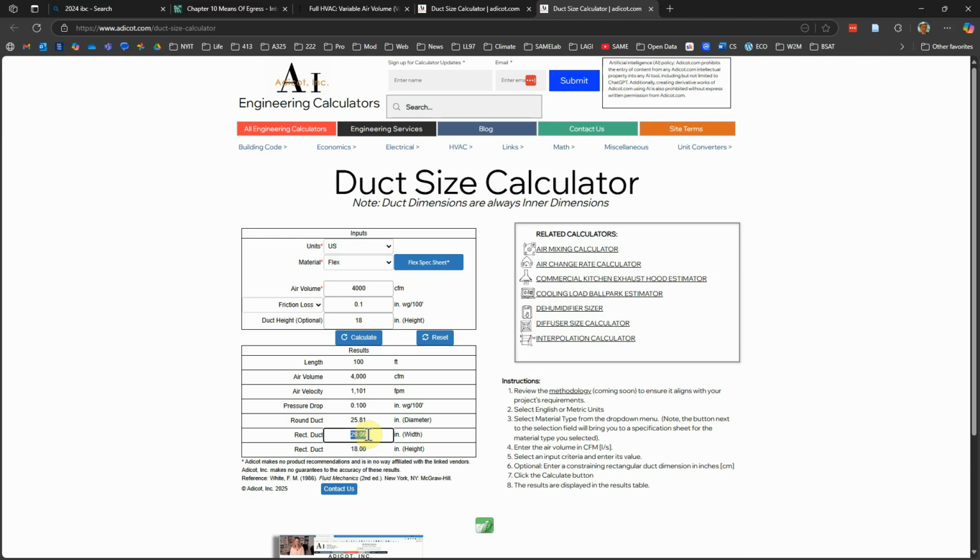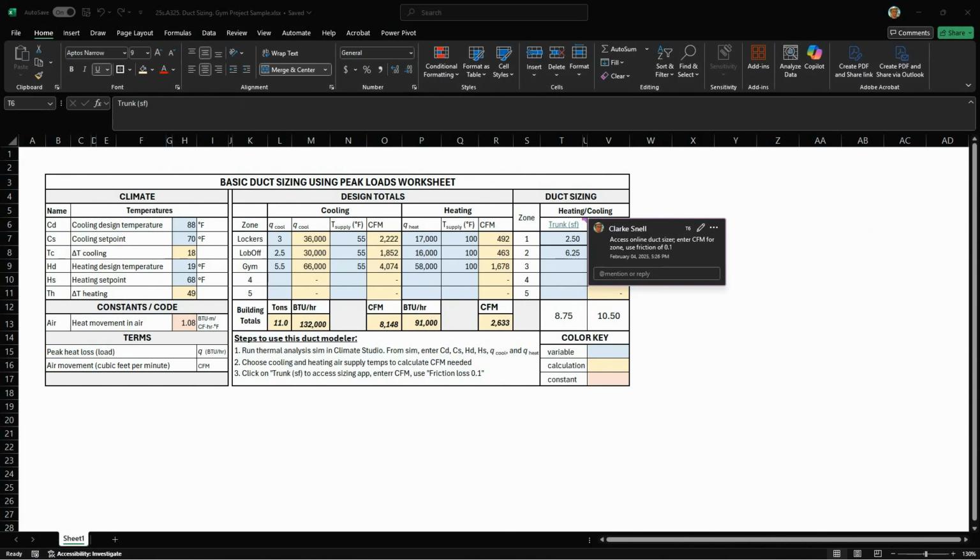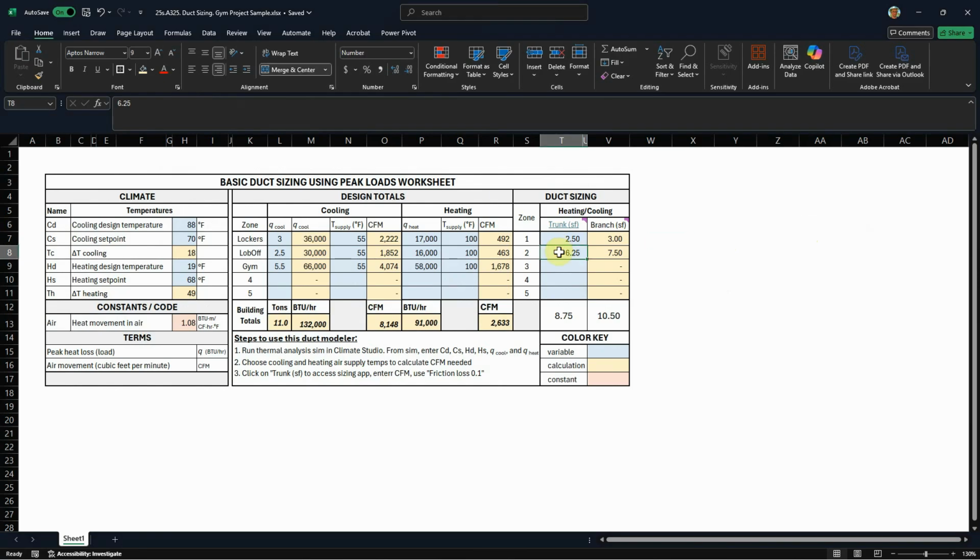We're talking about it's going to drop our ceiling height if we have to have more ducting. So we could also say, well, we're going to make it wider but flatter, less deep. So that's a control you have here. We take whatever variables we want out of there and put them into the spreadsheet here, and then our branch ducting is automatically calculated from that.